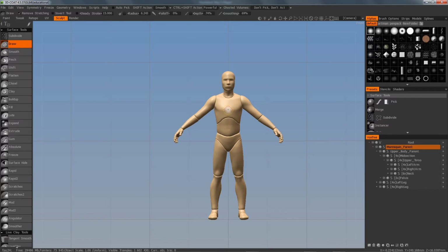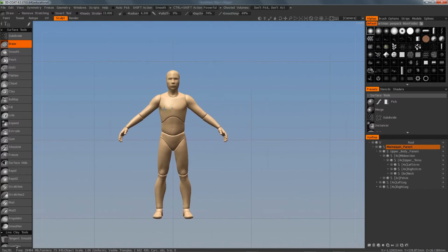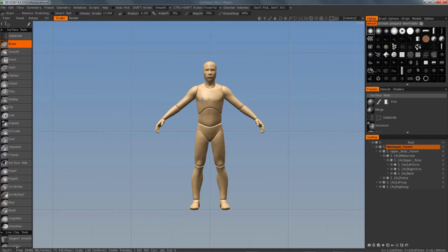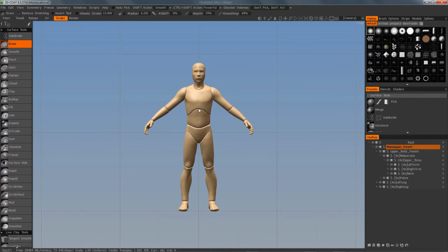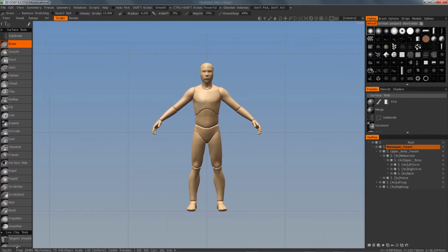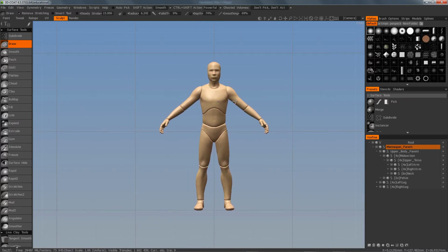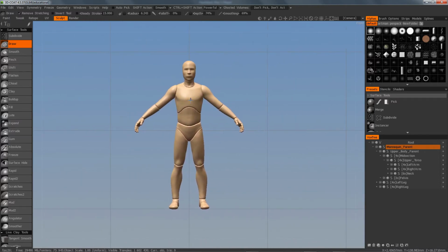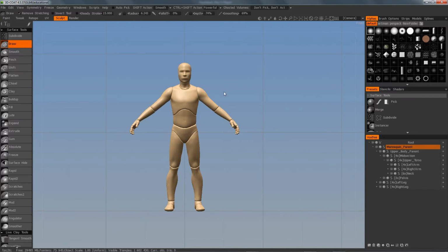And on top of the model, it's also middle mouse button. You don't have to use the Alt key. I recommend getting used to using the Alt key for all of the navigation, just because it's an easy habit to develop. But it doesn't need it for the pan. And zoom. Zoom is right mouse, click and drag.